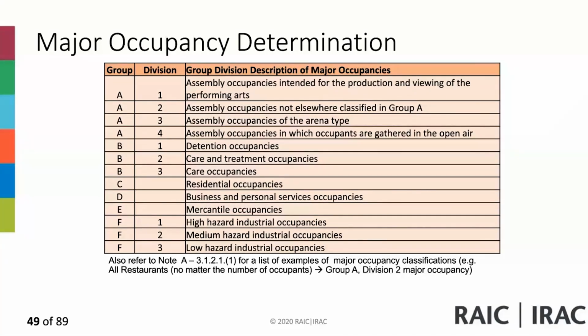It's on page 19. Low hazard means industrial occupancy in which the combustible content is not more than 50 kilograms per square meter. So that's for the combustible content, so it goes by combustible content of floor area. It's either in kilograms per meter squared, not more than 50, or in energy output, 1200 megajoules per meter square of floor area. So what would be low hazard industrial occupancy?